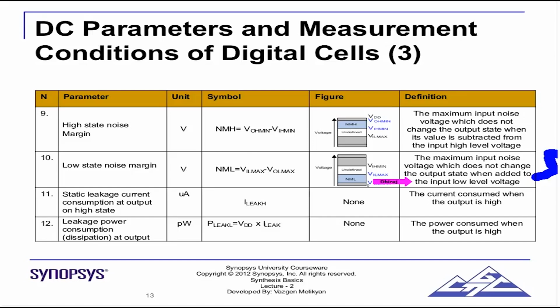We see that noise is part of static timing analysis nowadays in deep submicron technology. In fact, until about 90 nanometers, if I remember correctly, we did not do any noise analysis. We assumed the VDD levels were pretty high, 1.0, 1.5, 1.2 volts, and noise was not a big concern. So noise analysis was not part of our implementation.